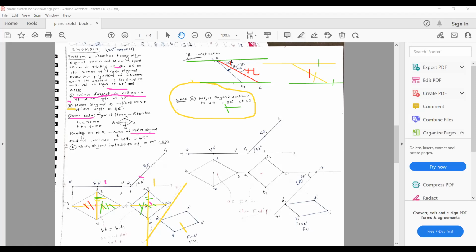or we can say the apparent length. Okay. So take the distance from this A point to C point in the compass, and keeping one end at A, the same point, cut this line with this kind of arc. Where it cuts, you will get the point.